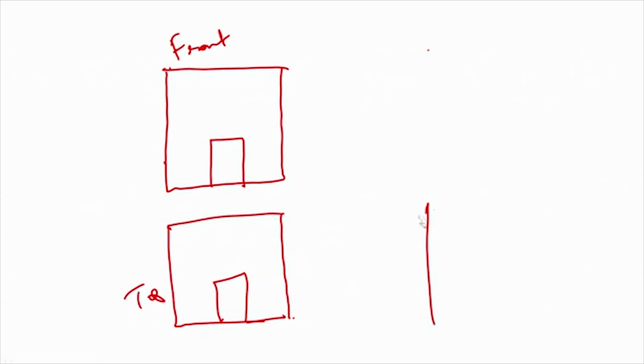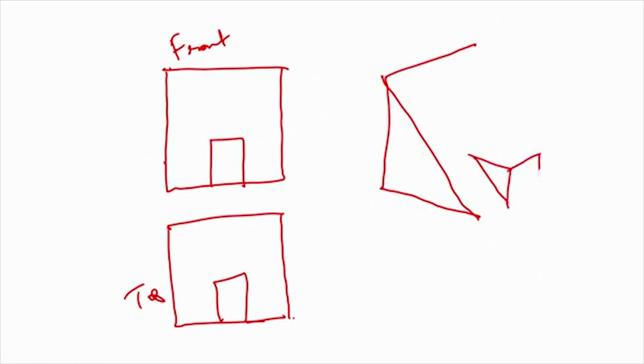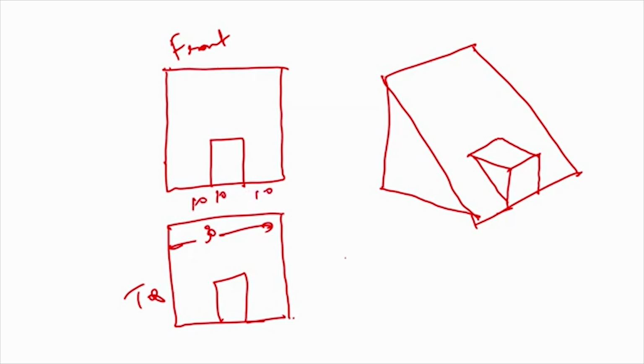Now, for convenience sake, I start here. Now, it makes sense, is it not? So, when I look from here, this is the feature we are seeing, and this is a detail about it. The only problem we may occasionally end up with comes to dimensioning, as discussed earlier. For convenience, I will take something which is very easy. I will say the width of this solid is 30 millimeters, and this feature is 10, this feature is 10, this feature is 10. Life is solved. Similarly, the height one more time, I write saying the height is 30 millimeters and this height is 10 millimeters.